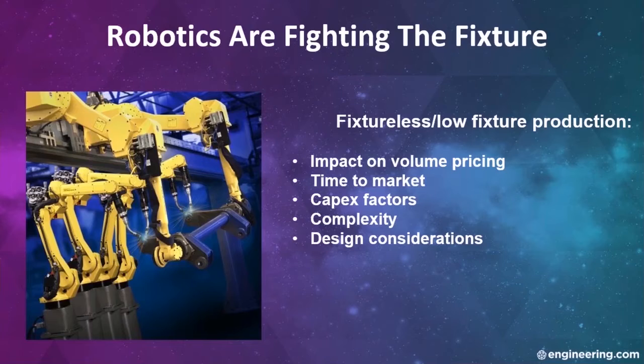Now, that repeatability usually scales inversely with the size of the working envelope, but we're seeing signs of integrated solutions that include things like machine vision and proximity detection with techniques like time-of-flight measurement. That's to enable accurate and precise feedback control positioning.